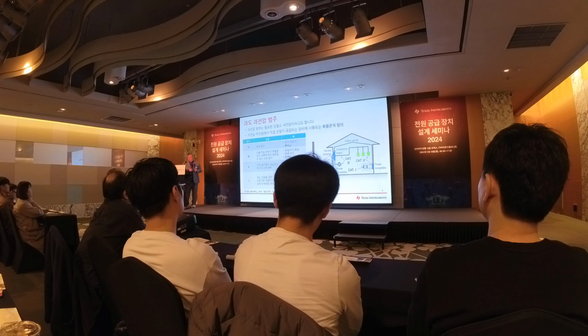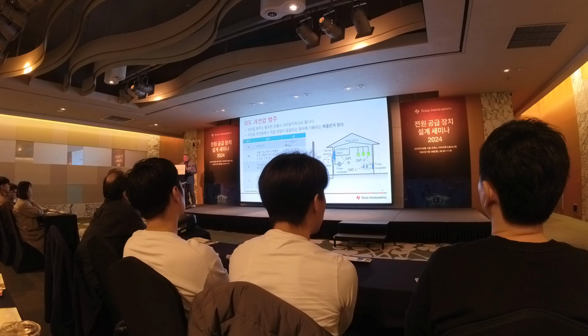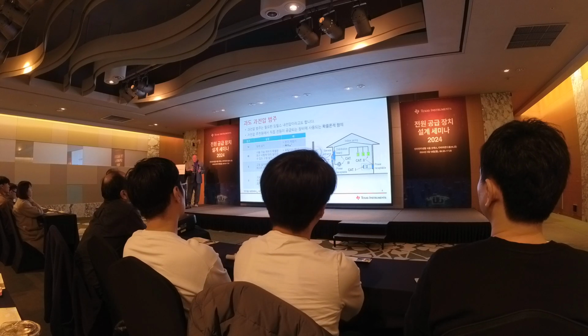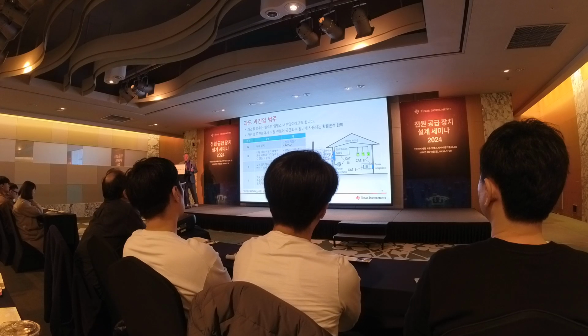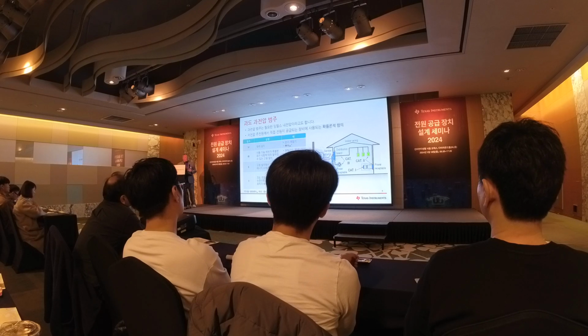Now, category 2 are plugs and various other items that are over a certain distance away. So these are outlets that are 10 meters or more away. And what you can see about these categories is as we get further away from the original installation, the transient overvoltage is going down. So for a category 3 source, we only need to have 1.5 kV peak transient voltage.